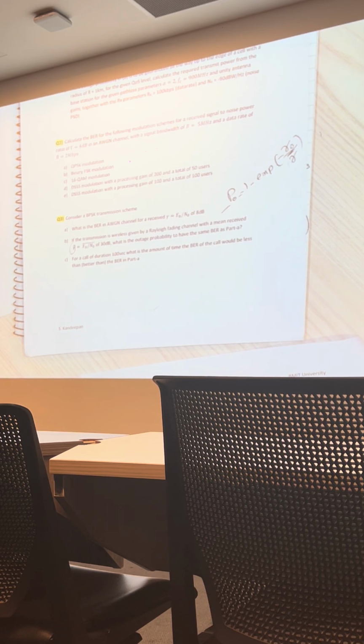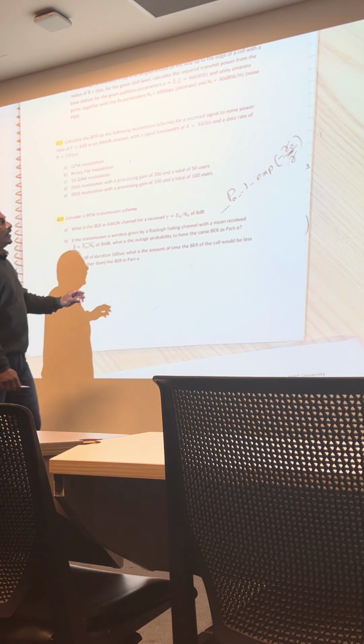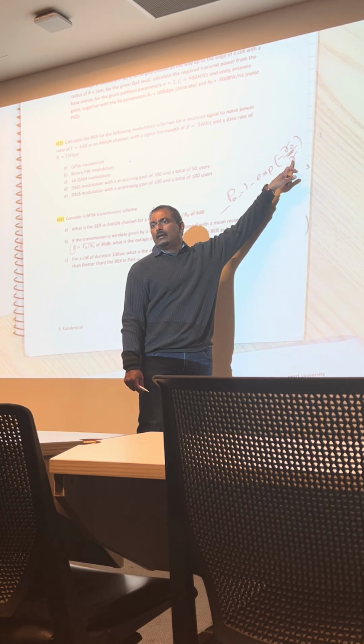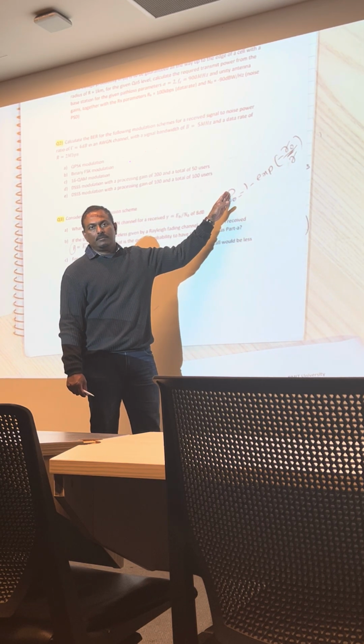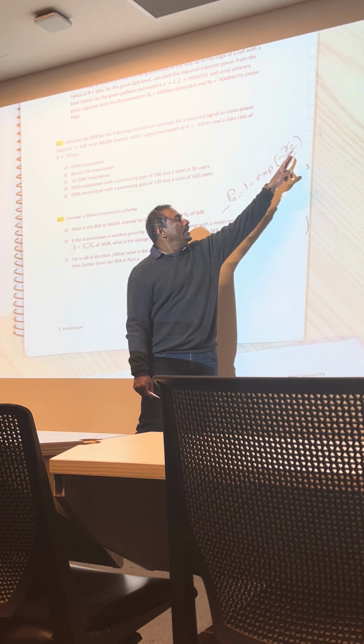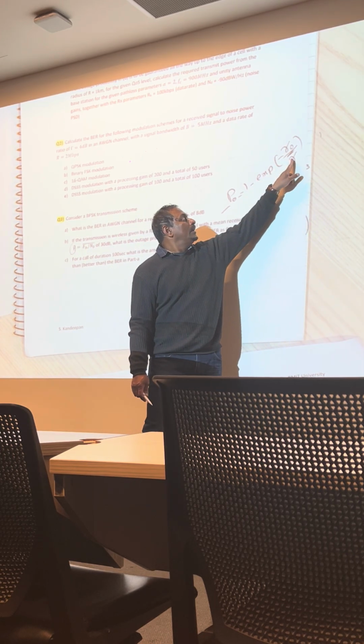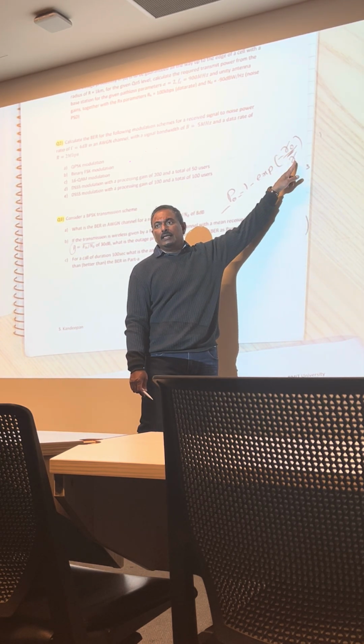All right, so what's the problem here in part B? It's a Rayleigh fading channel, so this is the outage probability expression for a Rayleigh fading channel. Gamma 0 and gamma bar are linear values. Gamma 0 is the threshold signal to noise ratio level, right? So in order to achieve gamma 0 in a gamma bar link, what is the outage? I'll repeat that again. In a link that provides gamma bar, and to achieve gamma 0 in a gamma bar link, what is the outage?